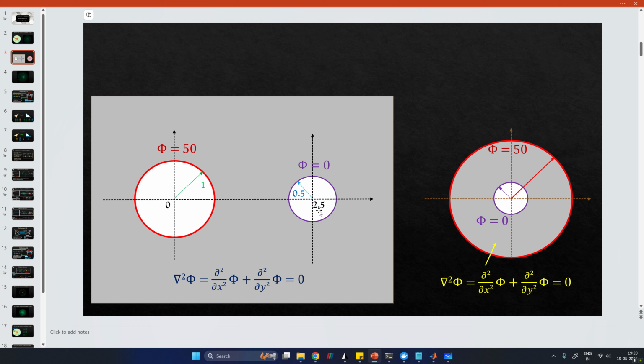So in this case, let's think of it as a heat transfer problem, because our objective is to calculate the secondary variable on these, to integrate the secondary variable on these boundaries. The secondary variable in case of heat transfer, or a diffusive heat transfer, is just your diffusive heat flux. In case of a mass transfer, it would be mass flux, and so on. So that is what we want to integrate here. And let's see how to do this, and we'll look at the reaction forces approach, which is very simple.